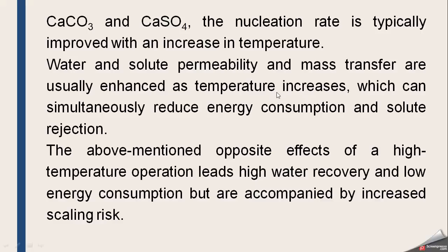Which can simultaneously reduce energy consumption and solute passage. In another video, where we already discussed the reverse osmosis system, we discussed the effect of temperature on the permeation or water flow quantity of the membrane, and we saw that by increasing temperature the permeate also increased, because now the molecules of the water can easily pass through the membrane.